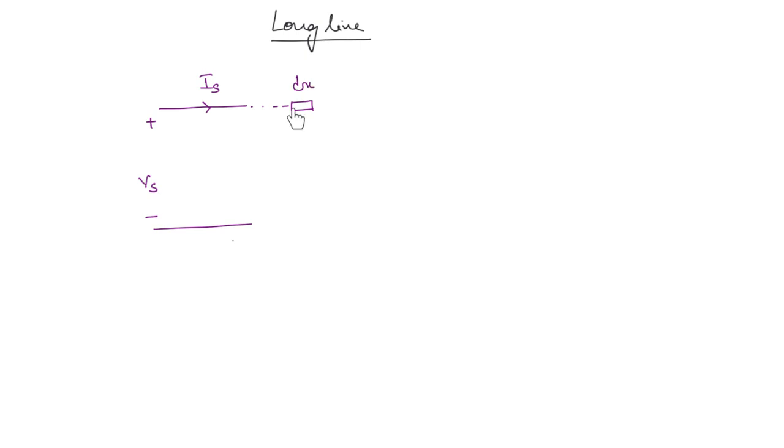This is the impedance element, okay, and here we can take the admittance, right, and this again will continue till we have the receiving end, and here the receiving end current is IR, voltage is VR. Now the voltage drop across this elementary element we will take as dV, right, there will be voltage drop all along the line. So across one elementary element we will take dV, okay, and also the charging current.